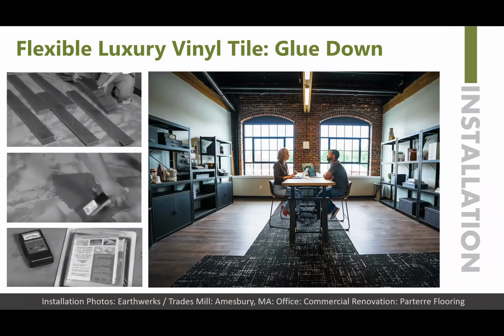Glue down installation methods involve the use of an adhesive to adhere your dryback luxury vinyl flooring to the subfloor. Using adhesive creates dimensional stability that ensures the flooring maintains its natural characteristics. The glue down method includes two distinct types of adhesive, hard set and pressure sensitive. Hard set adhesive is spread along on the floor, then the flooring is laid on top. Pressure sensitive is where the flooring product has adhesive on it and it is bonded to the substrate with pressure.